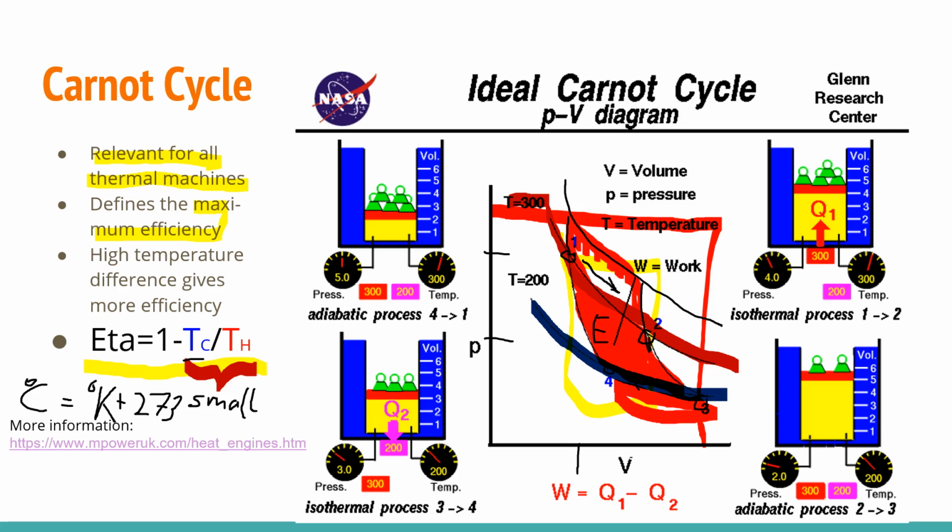And if you can't go colder than, for example, you typically use cooling water, maybe it's 20 degrees. So 20 Kelvin, no, not 20 Kelvin, 293 Kelvin, because that is 20 degrees Celsius. And the highest temperature, so look out for what your vessel can keep. You usually take steel, and steel works up to 600 degrees, maybe.